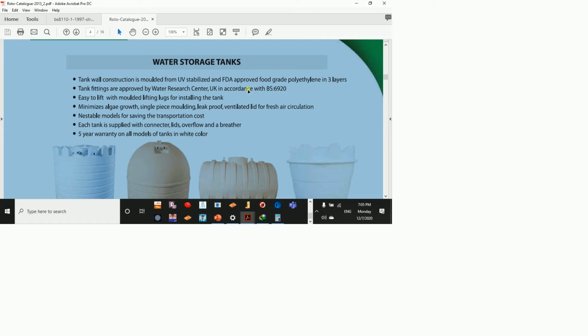So what we did was take a simple sample test. The column was designed for 40 MPa, megapascal. Eventually, we found it to be 15. At the time of testing, from 40, it was 15. It means that this building is going to fall at any time. So we reported that this building needs to be evacuated directly. It will fall at any time.